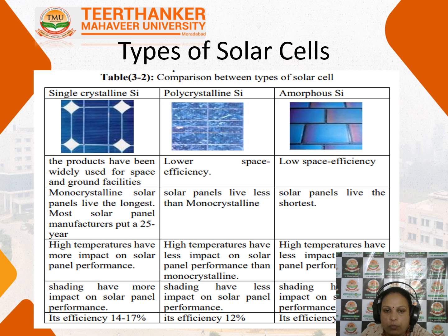High temperature has more impact on solar panel performance. So when the temperature is high, these solar panels are less effective. But in polycrystalline, high temperature has less impact on performance than in monocrystalline. Then in amorphous type also, high temperature has less impact as compared to the others.